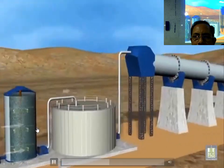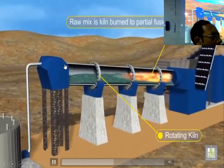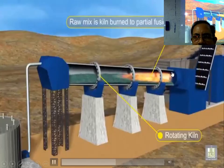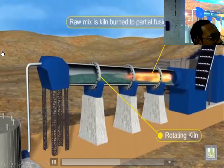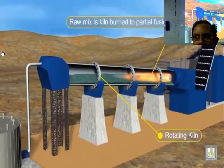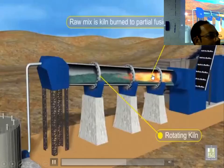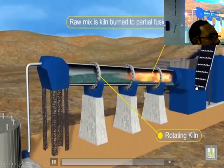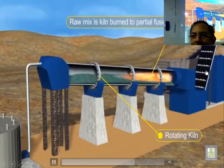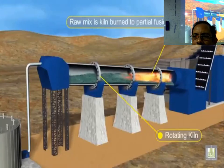The slurry is fed into the upper end of a rotary kiln, while at the lower end of the rotary kiln, the flame is thrown inside. This is the rotary kiln I talked about. Heating is done with direct flame, but inside, not coming out. The slurry is strongly heated until it reaches a temperature of 1450 degrees Celsius, producing clinker. Clinkers are formed here. The limestone changes by this blending and heating into new minerals, capable of reacting with water to form a cementitious binder.